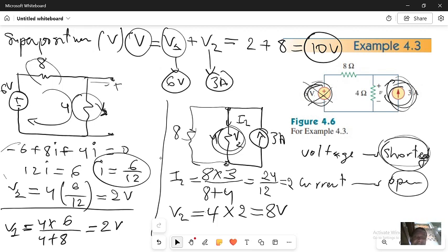So this circuit is like the property of linearity in the additivity, because in the beginning I have this source and I found V1 as output. Now I have this input, and I found V2. Now if my system's input is this one plus this one, then the output has to be the output of this one, V1 plus V2, as we see in the additivity.